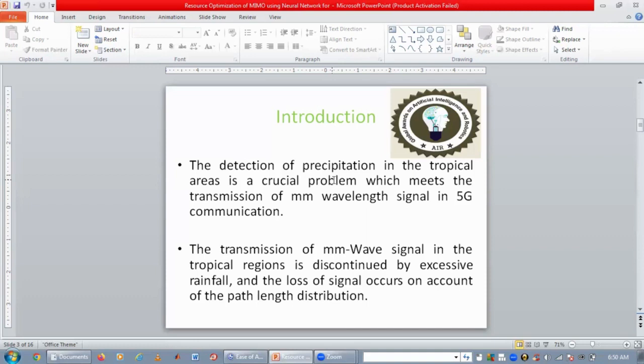In order to establish the framework noted above, MIMO technique has been applied to the design of microwave link, where signal fading appears very high. MIMO technique uses multiple antennas in both transmitter and receiver segment, and it is considered a key to 5G communication technology to minimize the system power and enhance data transfer rate. MIMO technology relies on the antenna diversity technique comprising various antennas placed on the wireless base station.